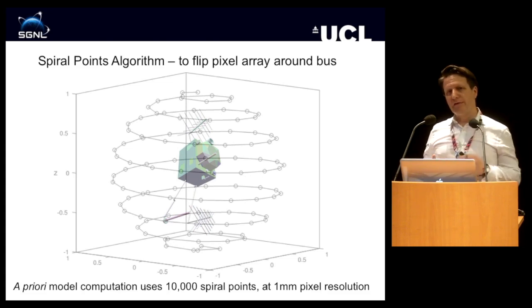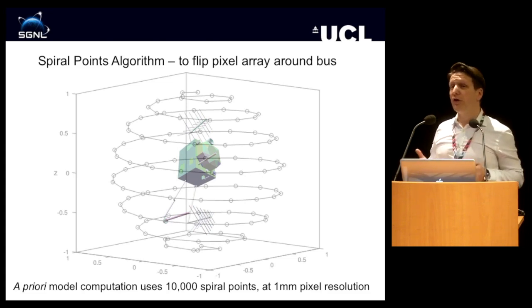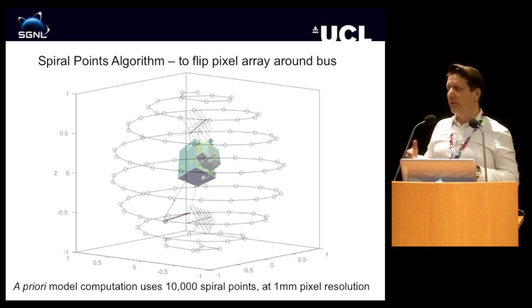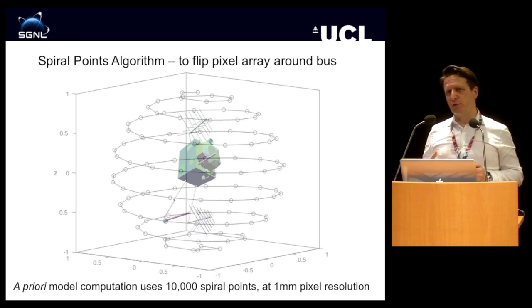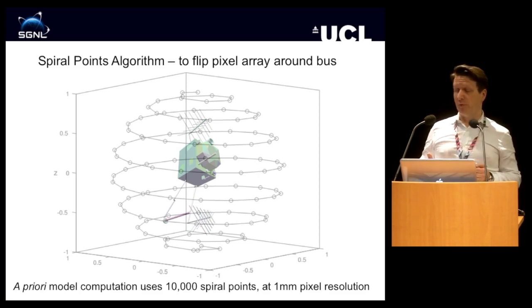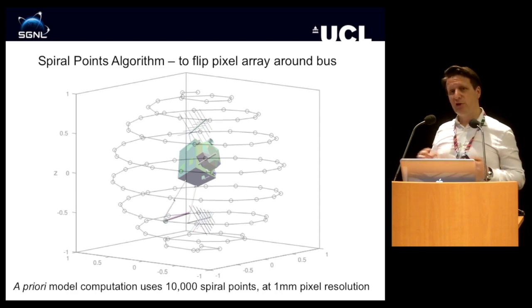So that gives us a sort of lookup table of the forcing on the space vehicle due to a radiation source of a particular energy in the body frame of the space vehicle. What we do to make this run fast when people are actually doing implementations of these models in orbit determination is we fit a continuous function to that data.